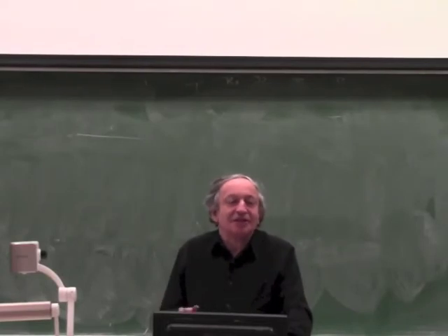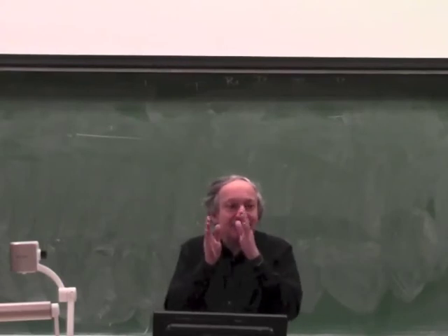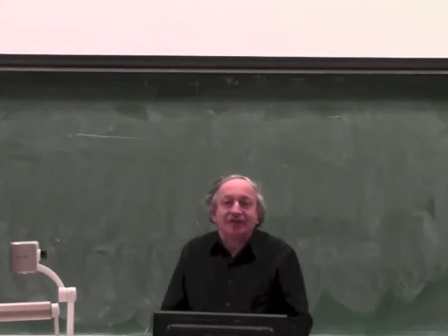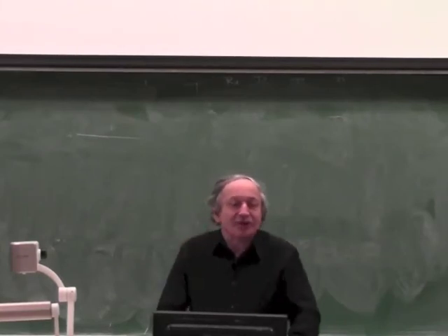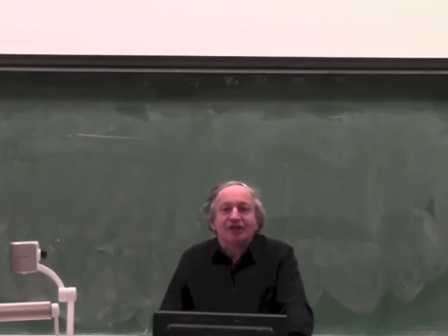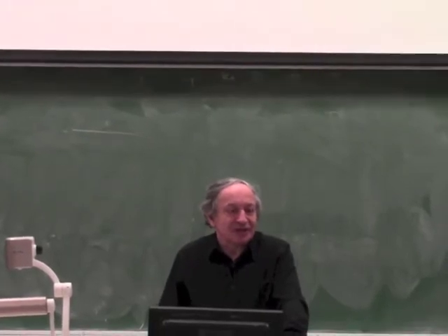That's the easiest. All you do when you make a MEMS is have a sacrificial layer, you etch it out, and you have a gap. And if you put a voltage across the gap, you get a force, and you can have a cantilever which bends and so on. So because of that, when you scale things down to very, very small, electrostatics are very useful, and because of MEMS, there are a lot of electrostatic actuators being used, so we'll devote one lecture to cover the theory of electrostatic actuators.